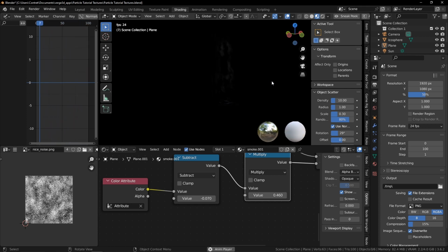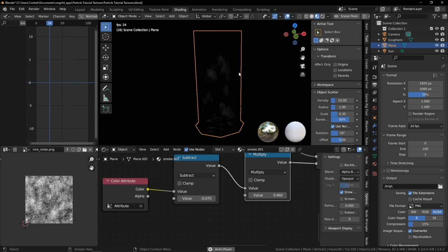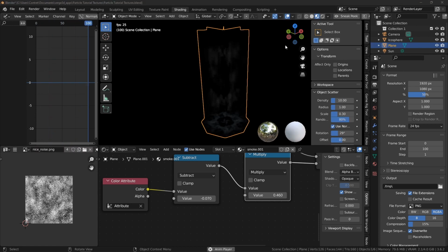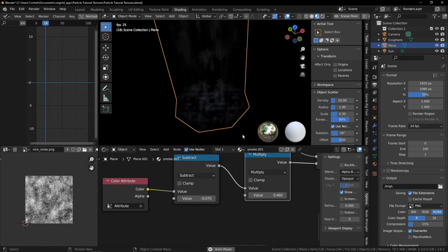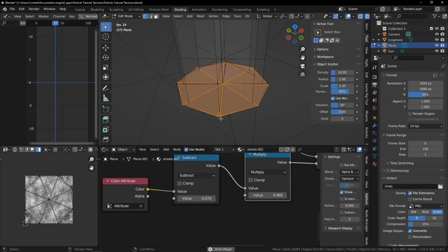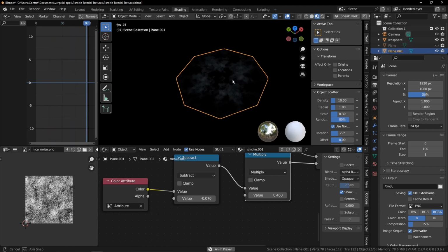Okay, looks good. Now we just need to copy everything, then paste it and shift UVs a little bit. I will leave it behind the scenes. Okay, here we go. The top part is done, but the bottom part is a bit too intense. We can fix it by selecting everything and going back to Vertex Paint to paint the center parts gray. I've also separated the bottom parts and hid the top parts for easier painting.